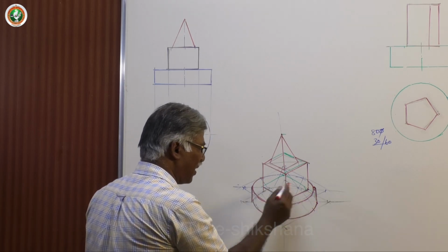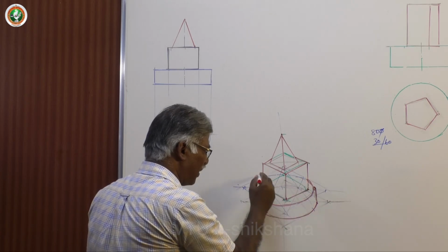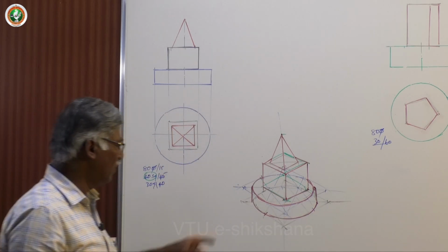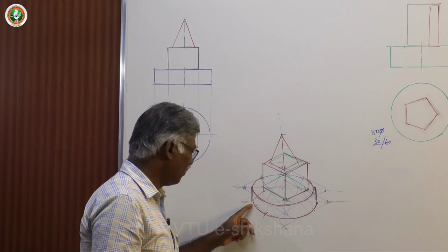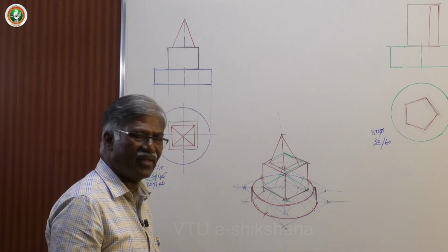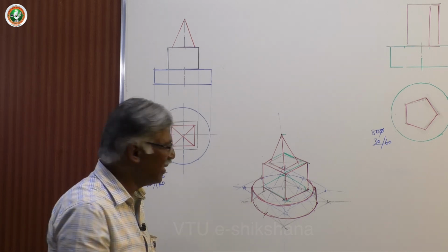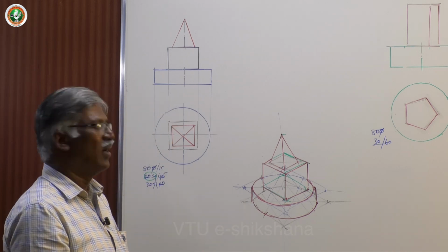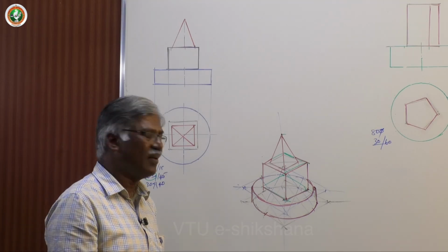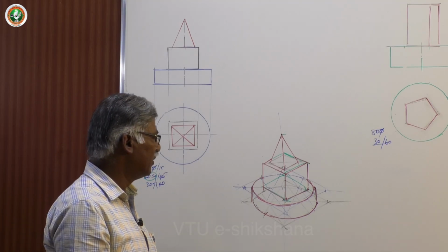Here you need not split, because here you have to split in the invisible edge for that. Here you have to split for visibility of the segment. So half of the segment is available, small radius. So this is how you complete the isometric projection or view. If it is projection, take the reduced length manually and work out.